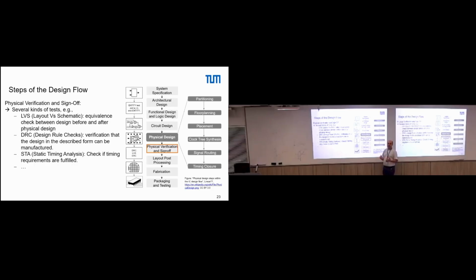But at the same time, the harder it is to simulate, because there is a lot more information. If running a physical simulation takes, let's say, minutes or seconds on a functional level, on RTL level, then on the physical verification level the same simulation takes minutes, hours, to years. So you just cannot simulate everything you could simulate before. Later, you cannot test as well.